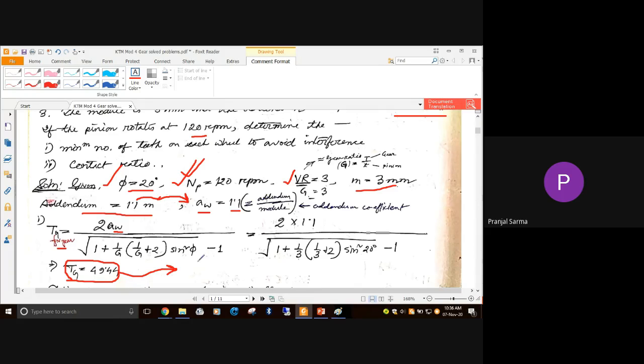And from the knowledge of the velocity ratio or the gear ratio, which is given as 3, the gear ratio is nothing but the number of teeth in the gear, capital T, divided by the number of teeth in the pinion, small t. So capital T by small t gives you the gear ratio. Now, if it has to be 3, then the t value we have just found out, for the gear, the bigger wheel, and the pinion, the smaller wheel, has to be divisible by 3.